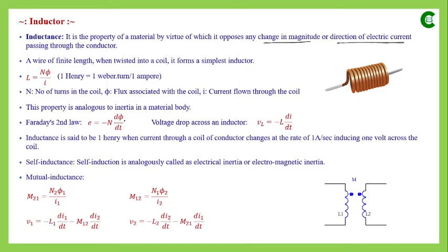So here, in place of phi, when we put Li by N, L by N will be constant, that will come out of the differentiation, and it will finally be di by dt, and already we have one N, and we will get the L by N parameter, and it will be di by dt, and that will be equal to the induced EMF. So finally this N and N will cancel each other, so it will be minus L then di by dt.